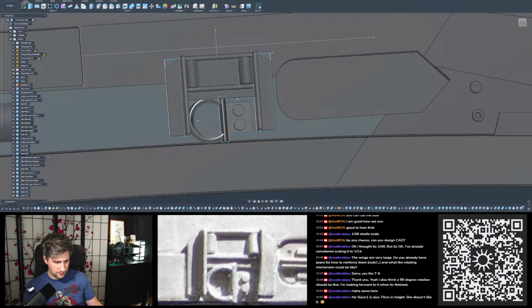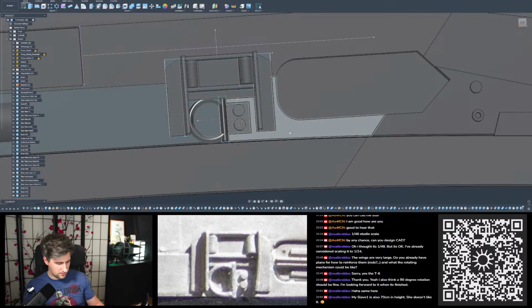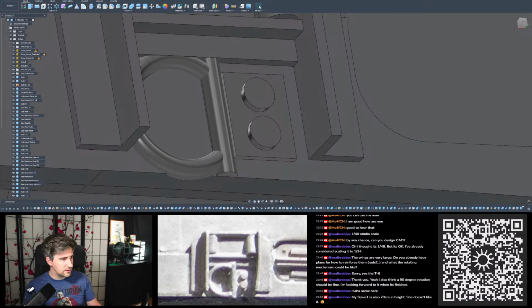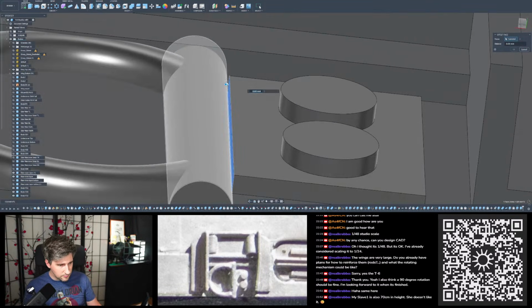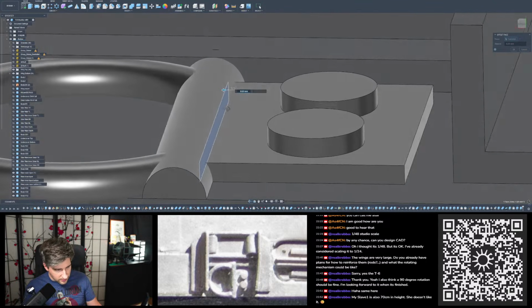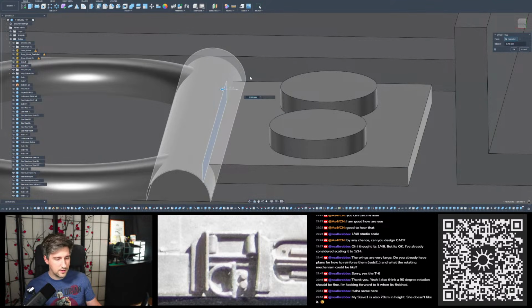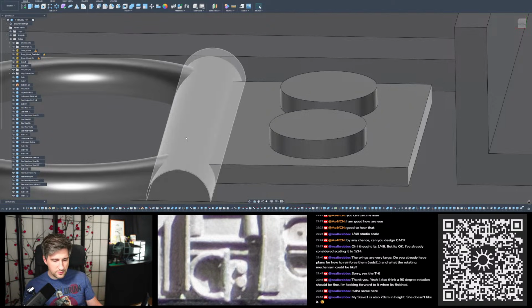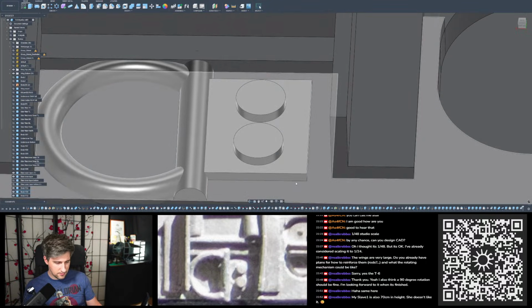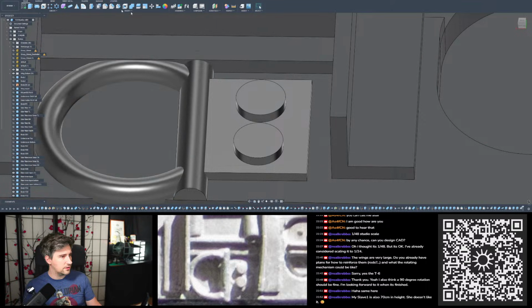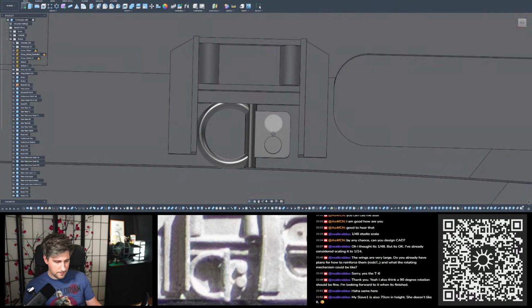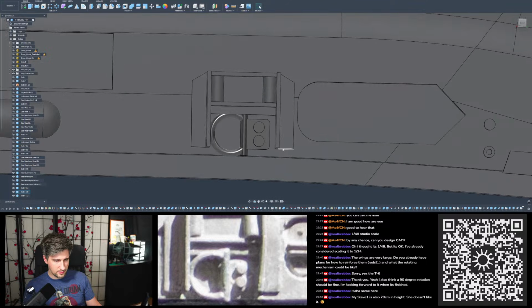Okay, now we have everything extruded so we can hide the sketch. Then we can see a little clearer here. I need to make this part a little longer so that it intersects correctly with this one. There should also be some fillets around here on the back. Let's make it 0.5 as we did on the other one. Okay, this is that.